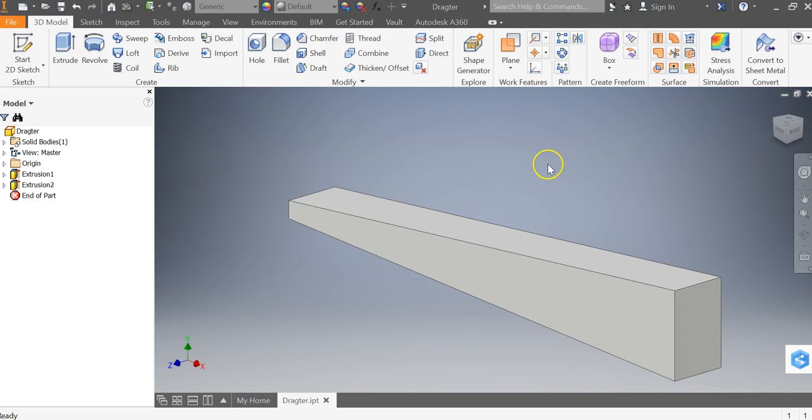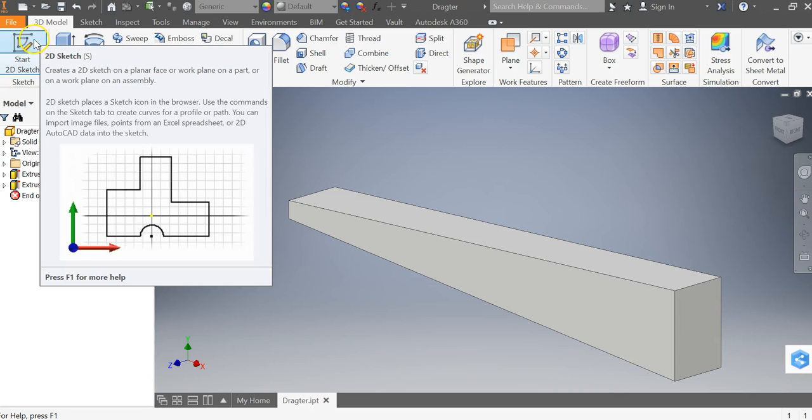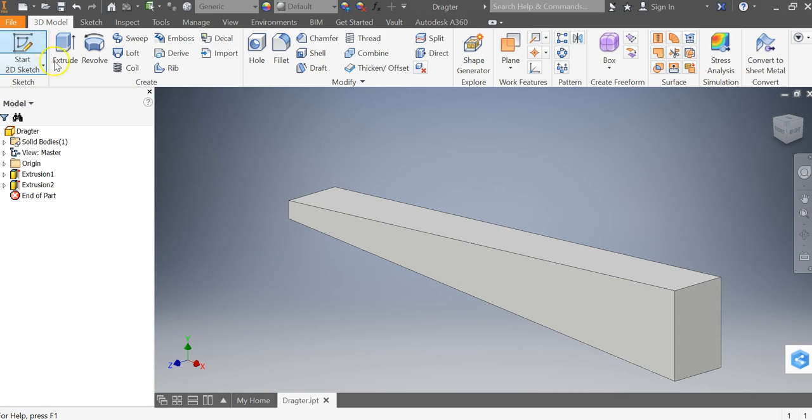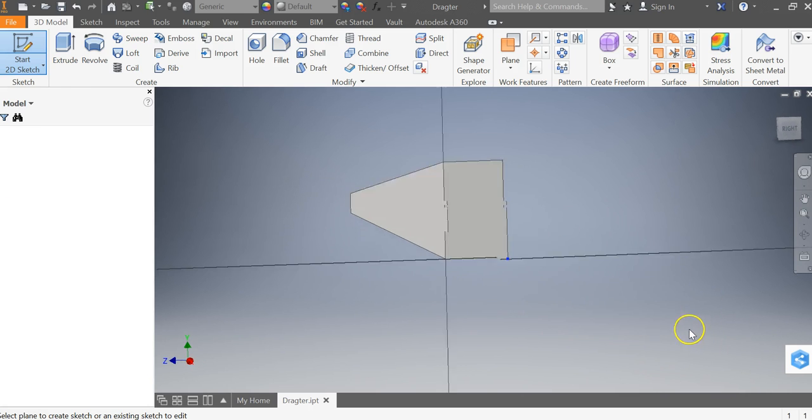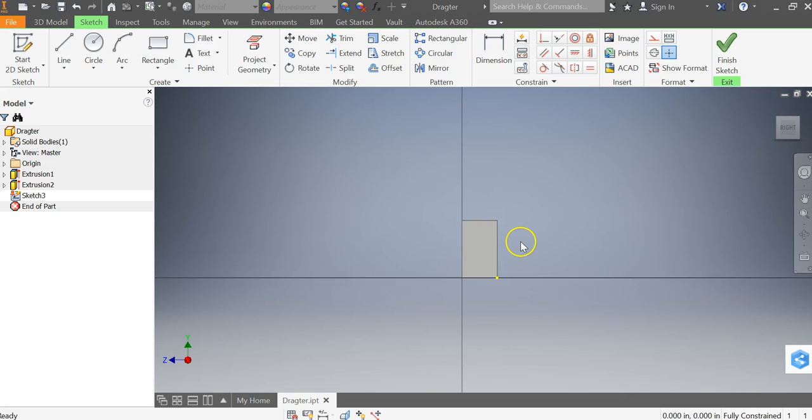The next thing that we have to do is create the hole where the air tube that we're going to use is going to be inserted. So we need to create a little hole here. I'm going to create the hole here in the back of the wedge. And once again, I'm going to create this by clicking on Start a 2D sketch. Then I click on the surface where I want to create my sketch, which is this section here. Once again, things rotate by themselves.